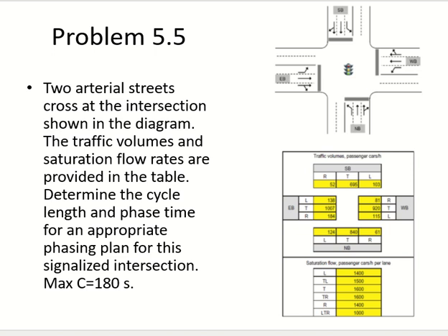So I have to divide it, and for division I will apply the same approach which I used in the previous question. This one will have less and this one will have more. Out of 1007, the one which is exclusive will have more and the one which has shared will have less. I'm using the same ratio, 45-55. So 55% of 1007 goes in this lane, the remaining in this lane, and this lane will also have the right.